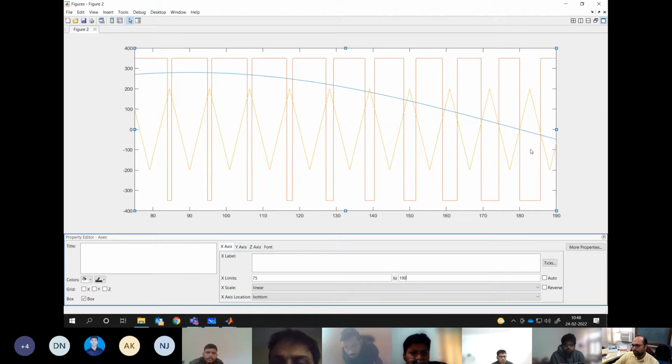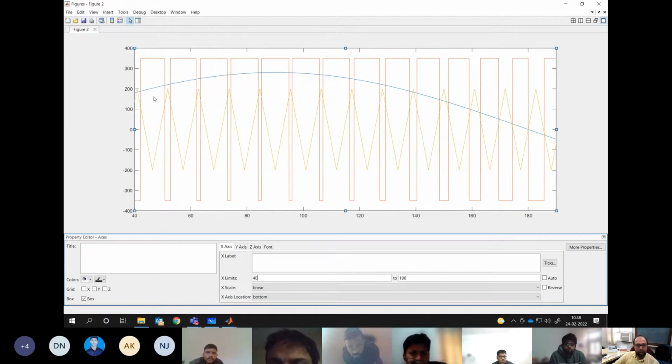Understanding my point? So all the way from the highest, so if you go a little bit on the lower side, you see that this pulse width is increasing. It has become maximum somewhere here, and then it is gradually reducing and coming down to equal, plus VDC by 2 and minus VDC by 2. This is how we are realizing the voltages, average voltage in the pole voltage.